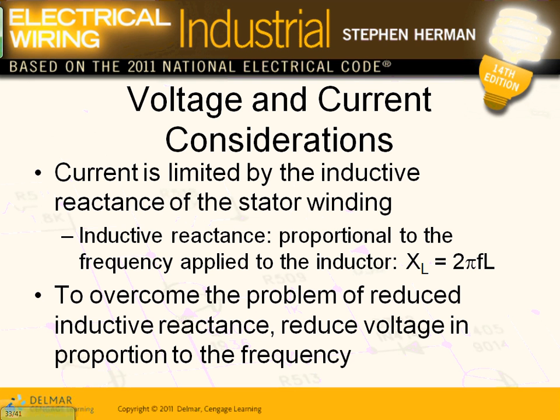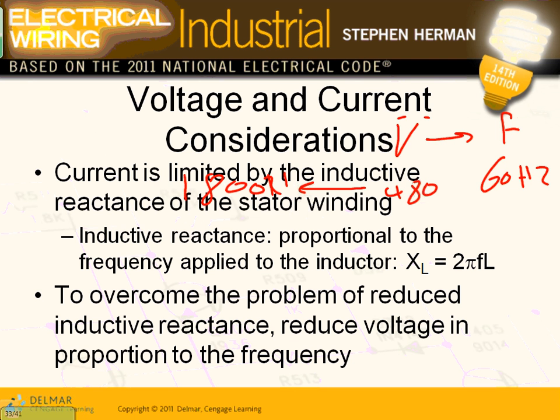Here's voltage. Here's frequency. I have 480 volt and I have 60 hertz. If my motor, Chris, runs at 480 volts, 60 hertz, out of this outcome, let's just say synchronous speed, I can get 1800 RPM, okay?